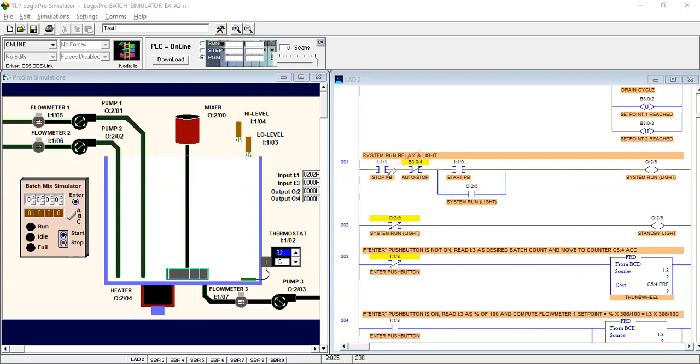One is the stop push button, and there is one auto stop button. This is the internal event. Auto stop: it stops the automatic mode if you select the auto mode using the selector switch. After that we connect the start push button, and this is our holding. Okay, this is our holding.